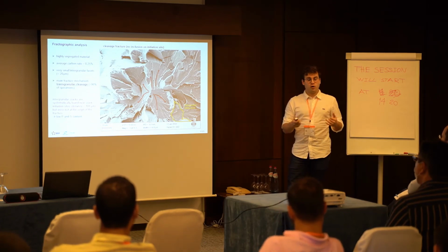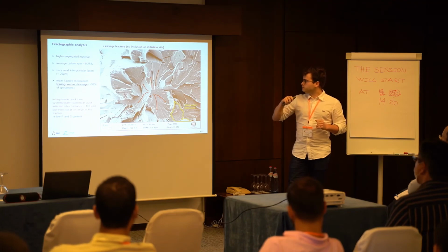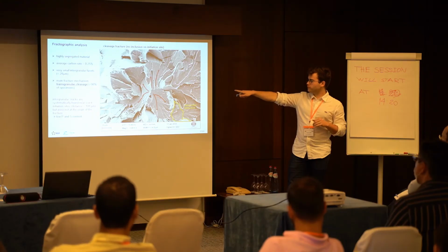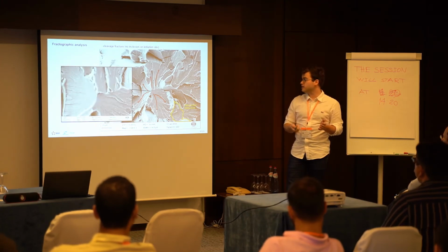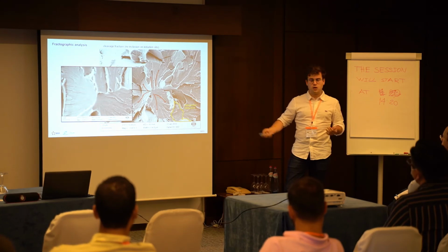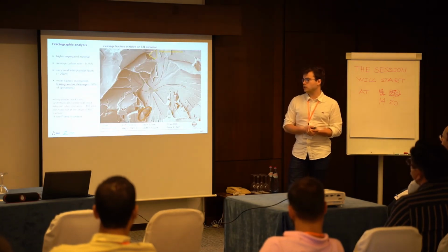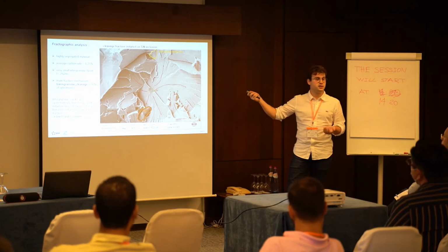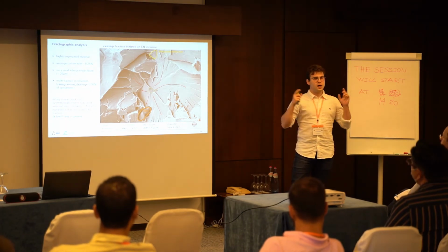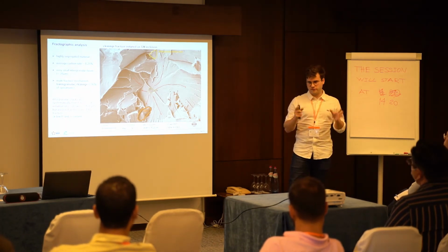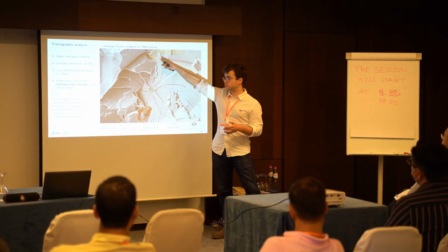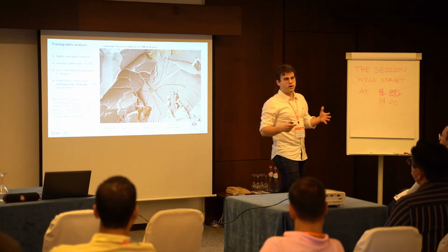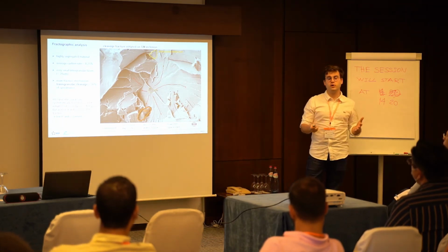The initiation of fracture could be either on nothing that can be identified, such as here, or sometimes on inclusions, such as titanium nitride. However, we systematically found near crack initiation sites small intergranular brittle facets, although they are never at the origin of the specimen's fracture.